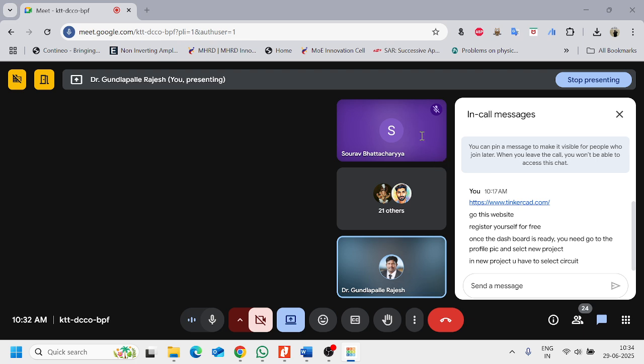LED. Next, the same variable has to be used further, right? So the pinMode is the output mode, and the pin which is defined as an output port is the seventh pin. Suppose you want another LED on another pin, then I'll make it LED 1, which is equal to say the 8th pin, or I'll make it the 12th pin. Now whenever two pins are to be configured, the same thing has to be defined in your setup as output. So this is your LED 1. Now this is your setup.